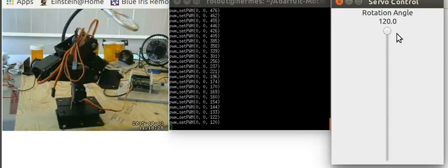You can use this program to determine the min and max values of your servos by using the slider. So if you were to change the parameters from 120, 530 to say 110 and 540, you could use the slider to go to those values.